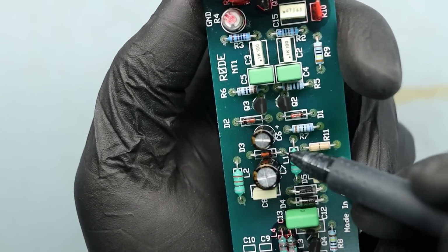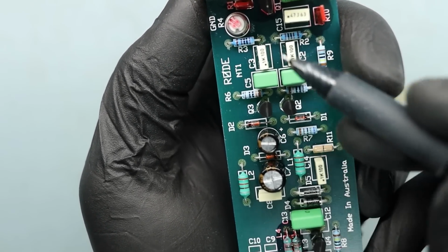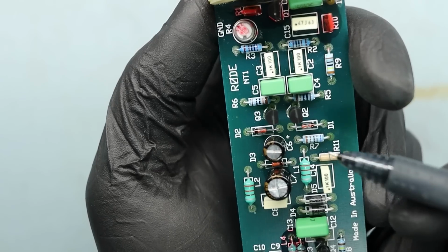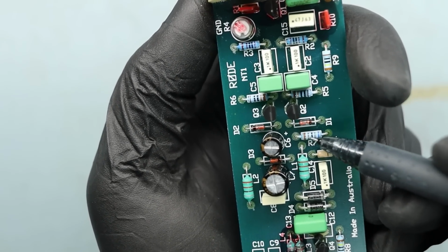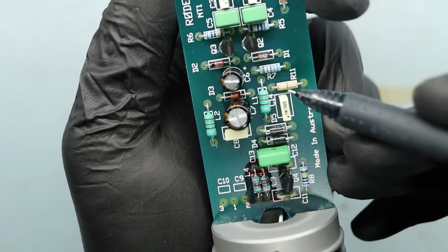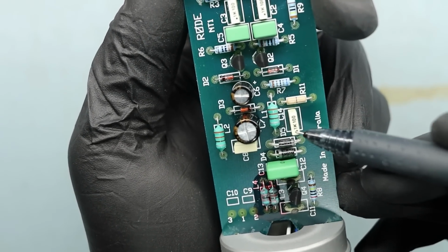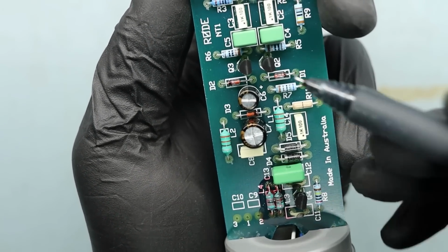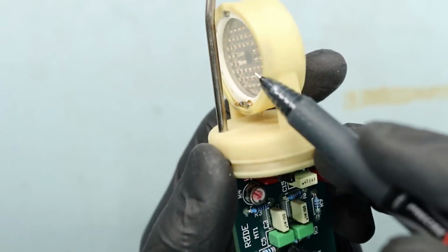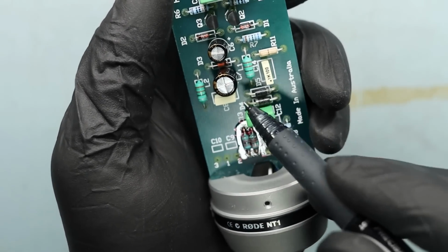Then we have this 6.3 volt Zener down here. That sets that voltage up for the rest of the circuit, for the transistors to operate at. This is the filter capacitor for it. R7 sets the current through that Zener. And then we have this boost circuit. It takes that 6.3 volts and bumps it up to 48 volts. It can do that because we don't need a lot of current to keep a charge on this. We just need a high voltage, so there's not a lot of current being consumed there.